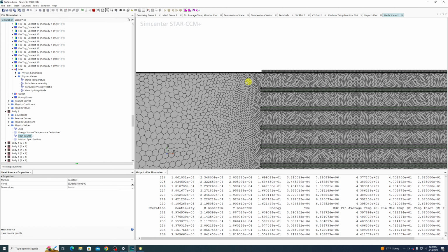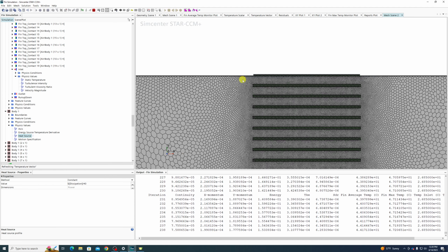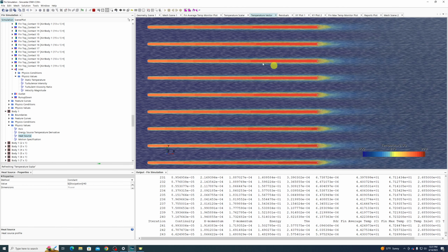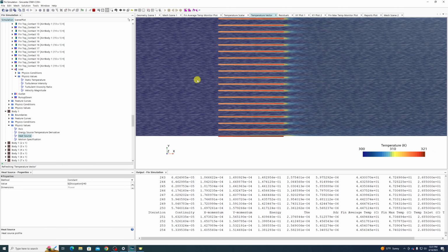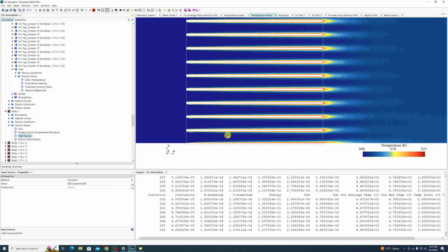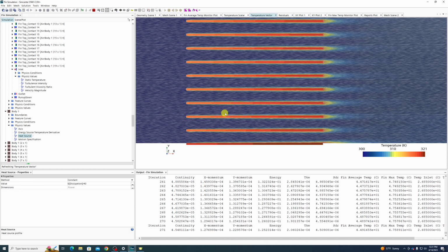But this is a thermal interaction between solids, the fins, and the fluid that is taking thermal dissipation. It's adding heat to the fins, about 100 watts, a little bit less per fin, and ultimately it's saying, hey, the solid warms up, you're adding heat to it. The solid is touching the air, so some of this heat gets transferred to the air. The air heats up and carries that heat away. So this is a solid fluid thermal interaction of a fairly typical cooling stack.